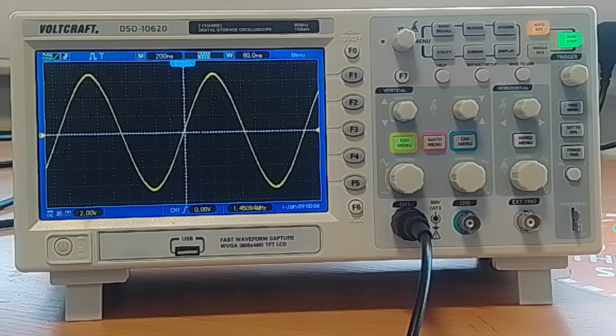The other thing you can be asked to do is to work out the average for voltage. And so again, you take your 6.8 and you multiply that by 0.637. Gets you 4.3316, which you'd probably round to being 4.33. That would get you your three significant figures.